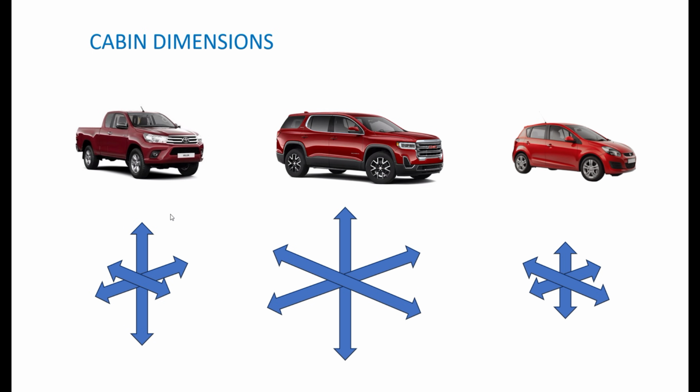And of course, throw into that where your driving position is. In the pickup, the driver is physically closer to the windscreen than maybe in the SUV, right? How close you are to the windscreen and the side windows, and that type of stuff will affect reflections. How you hear reflections and things at the driver's listening position.